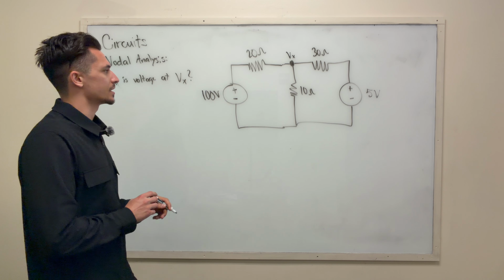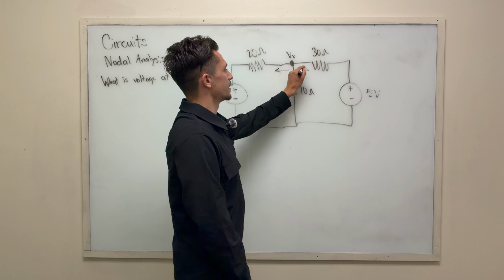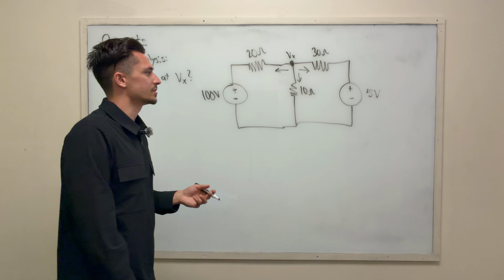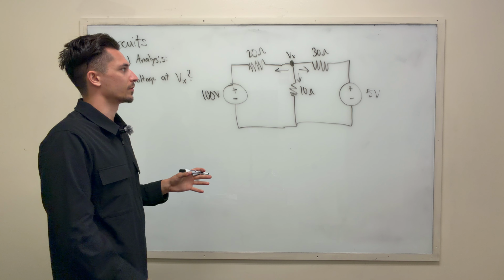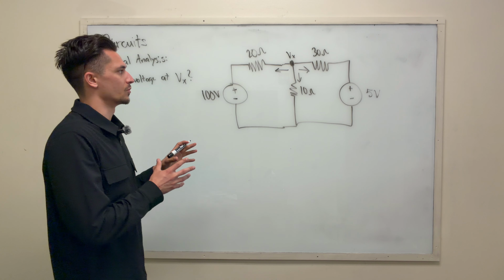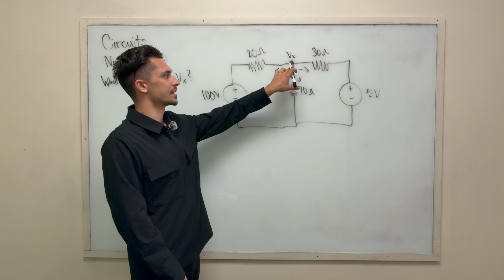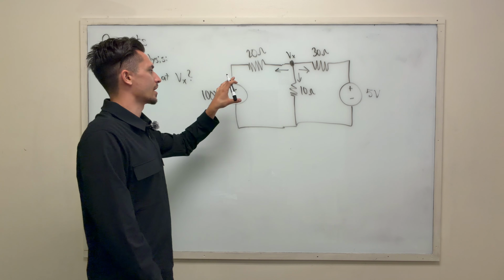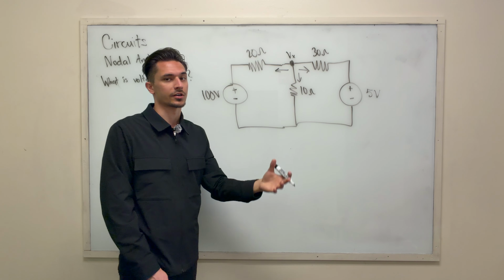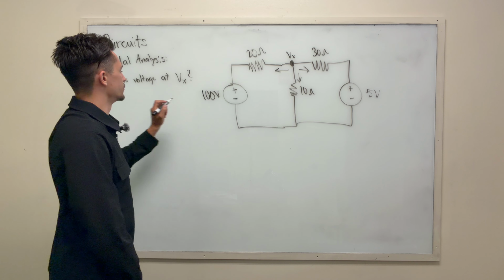When we're trying to find the voltage, my recommendation is having arrows pointing out this way. The reason I like doing this is because we can organize our thoughts and the way we would format this problem. What these arrows are saying is that I'm going to take this voltage, subtract this voltage, and divide by this resistor, which will give us a current, right? If we go along and try to solve it, for this side, what we do is